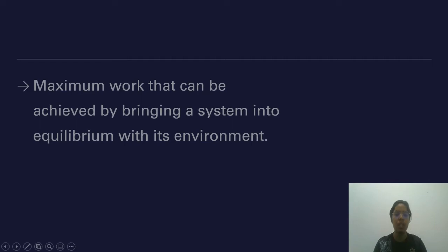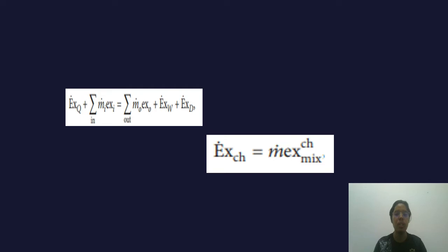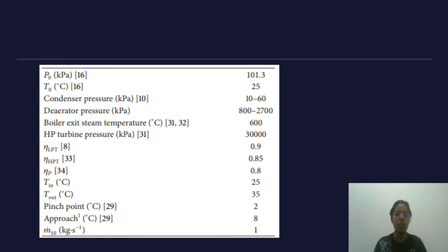Exergy analysis is one of the most useful and applicable tools for thermodynamic analysis to perform calculations on the system. These two equations show in general the exergy discharge and the exergy at any state of an open system, where EXQ, EXW, and EXD are the corresponding exergy of heat transfer, work, and the exergy discharge. Next, to perform the calculation of the system, exergy discharge D is the main parameter for all components of the cycle.